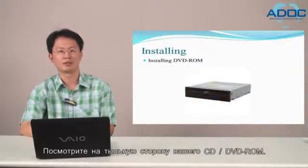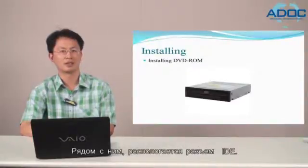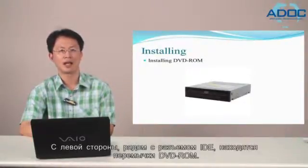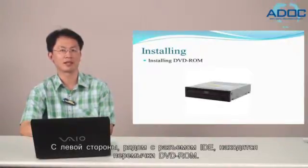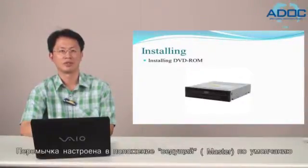If you look at the rear side of your CD or DVD-ROM, on the right-hand side, you have the power connector. Next to the power connector, you have the IDE connector. On the left-hand side near the IDE connector, you have the jumper settings for the DVD-ROM. The jumper is set to master by default.